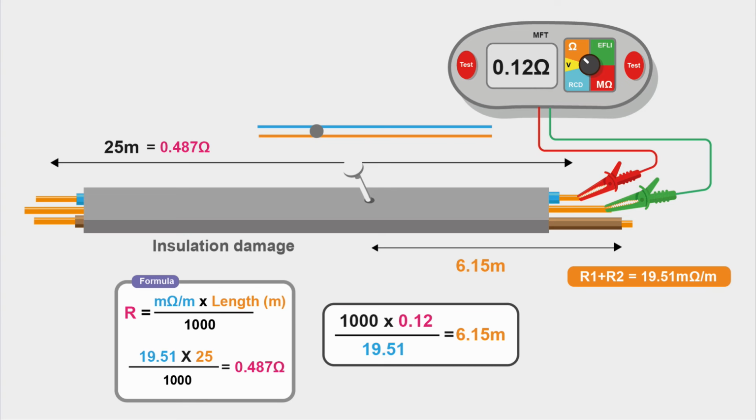Imagine if a nail's gone through a conductor. This could have happened some time ago, but it's only starting to show as a fault now. You might have installed an RCBO or something. But you think, what's happening? We've got a short circuit. The neutral earth loop has been shortened by the nail through the cable, and this will make an RCD trip all day long.